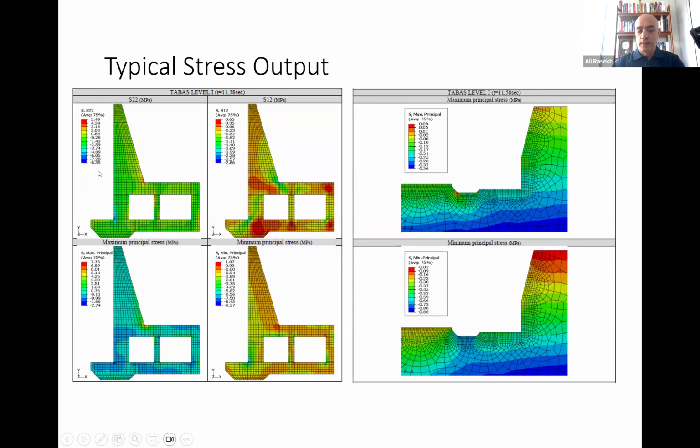So you just really go by section design and check sections for section forces rather than localized stresses, like your beams and columns in the structure. But the programs, and Abaqus is the same, allow for output of section forces. And then you can use your Canadian or US standard or international standard for design of the concrete sections.